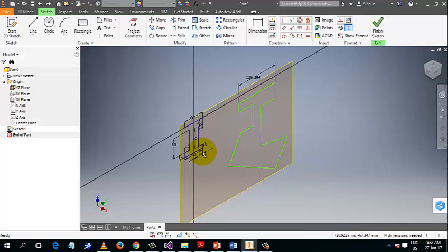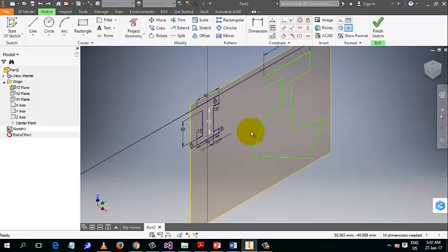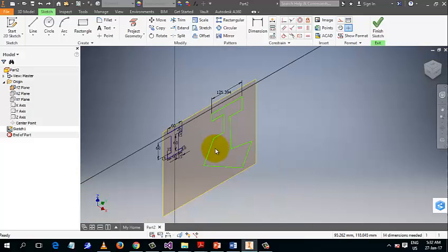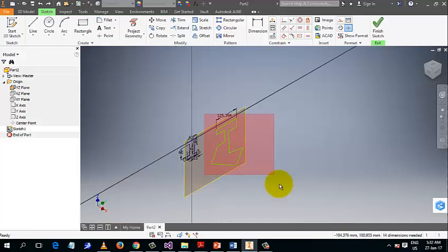You can draw something near the redrawing. No, this is too rough. That's why it's been distorted as I'm trying to constrain it. You can try to draw something near the redrawing. Then later on, you begin to constrain it using all these tools. And that's why dimension is also placed under constraint, so that you can use dimension and so forth to constrain them. So that's what I want to show there. Now let me highlight all this and delete it by pressing delete on the keyboard. Okay, let's continue.